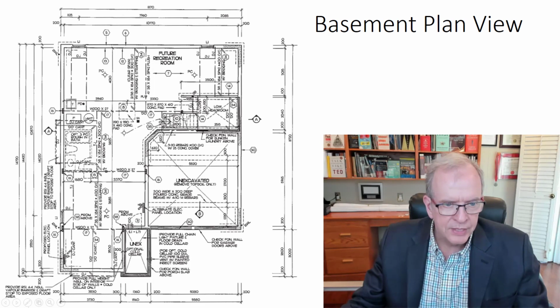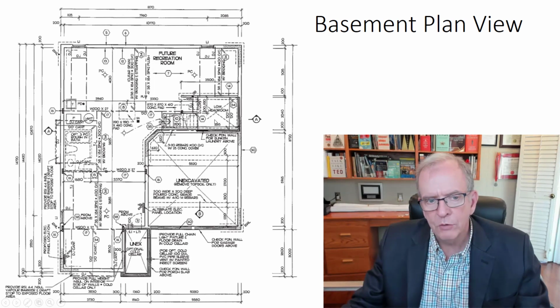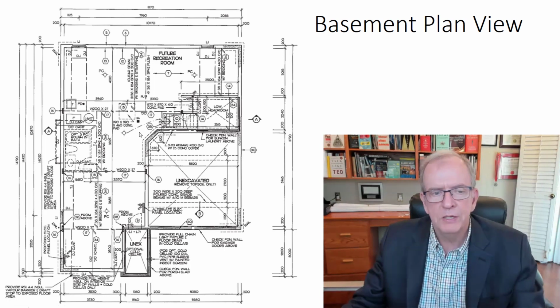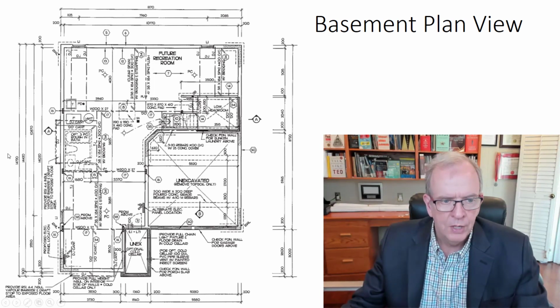We see here we've got a staircase that's going up, and this says up 13 risers. Way later when we look at this, or I think even in the previous video I talked about that, it actually goes 11 risers up to the landing and then 2 more risers up to the first floor for a total of 13 risers. That's just how this designer does it. Others may do it slightly differently. They might have shown 11 risers up to the sunken landing and just kept it that way, but it's okay. Once you get used to however the designer is doing things, it's pretty easy to follow.